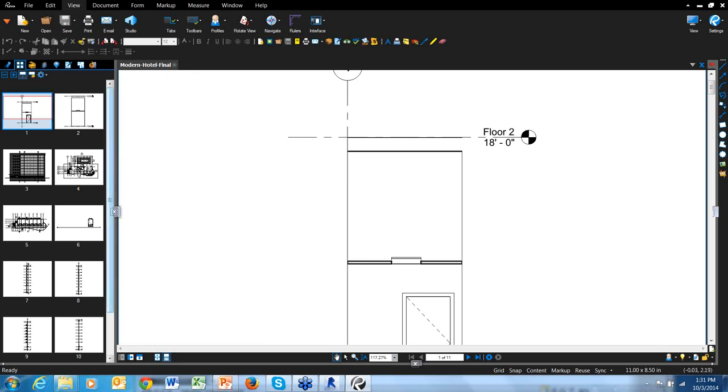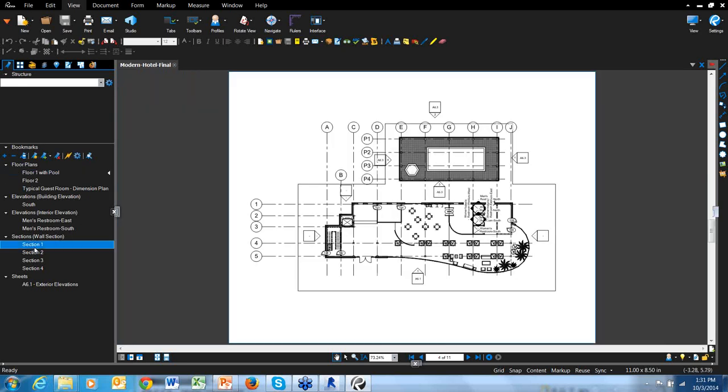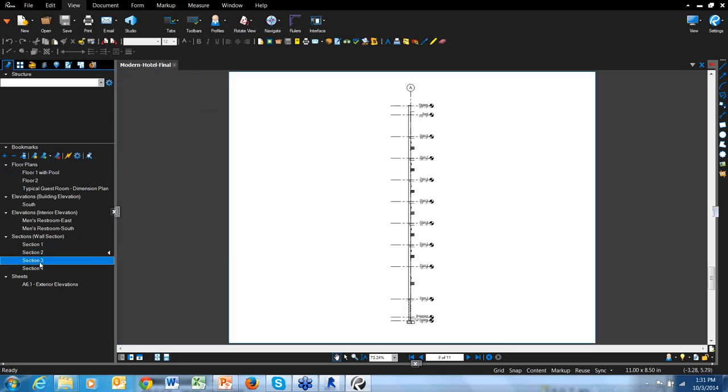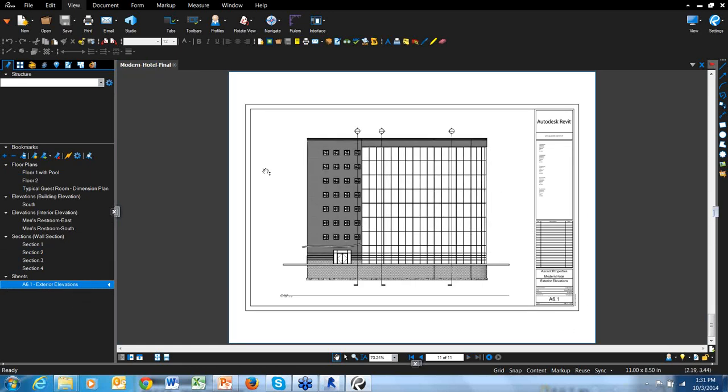the Bluebeam PDF. And then I've got a list of all of them. That's when I first started, I had the table of contents over here if we look at the bookmarks. And so first of all, you can switch just by choosing anything in that list. I can switch between my different views or the sheet that I printed.